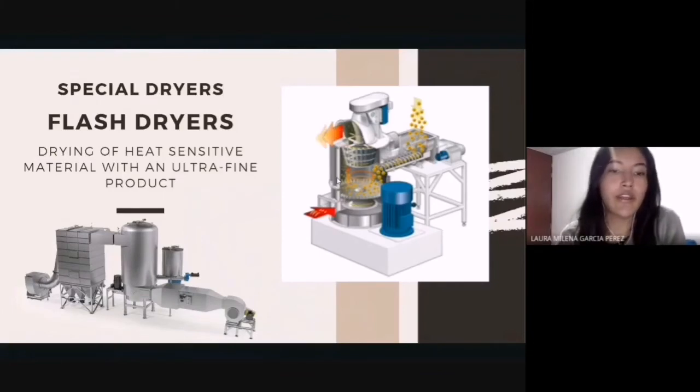The operation: in the color image, we can see the wet feed mechanically dispersed thanks to the impact of energy generated by the motor. The particles are in sizes of 10 to 5,000 microns. A controlled hot gas stream from the air heated by the extraction fan passes through the main body and fluidizes the fine particles in the chamber. This ensures optimal heat exchange and instant humidity evaporation.